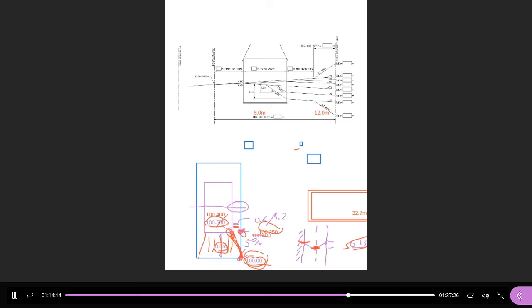So that elevation here is going to be negative 2.165. And then what would the elevation at the back of the lot be if we were going to maximize the 3-to-1 slope? Two decimal places. Negative 3.89, that is correct, okay?